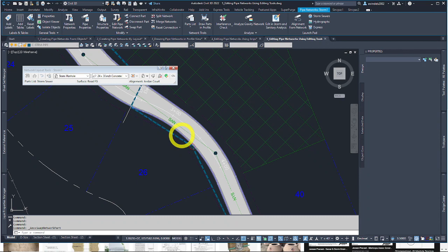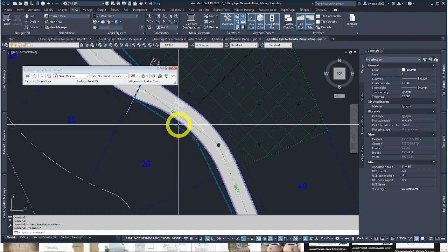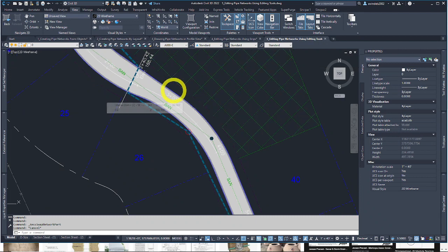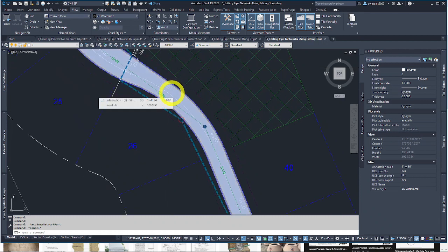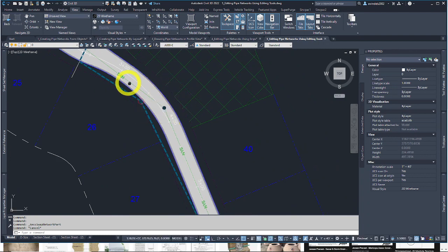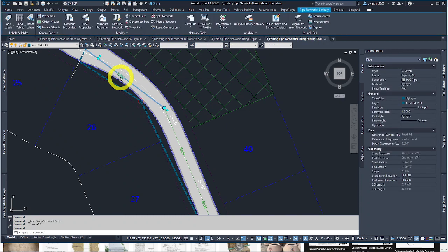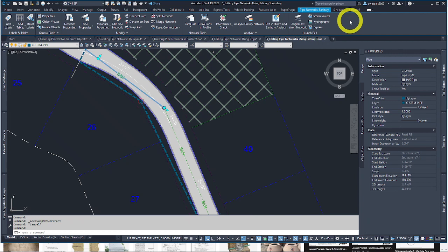And I'm going to hit escape. And I'm going to close the network tools toolbar down for now. And I'm just going to click one of the sanitary sewer pipes in the drawing, so one of the green pipes, the sewer pipes. Let's click just one pipe, or structure, will do. And let me get my pipe network's individual network contextual ribbon opening up because of that.